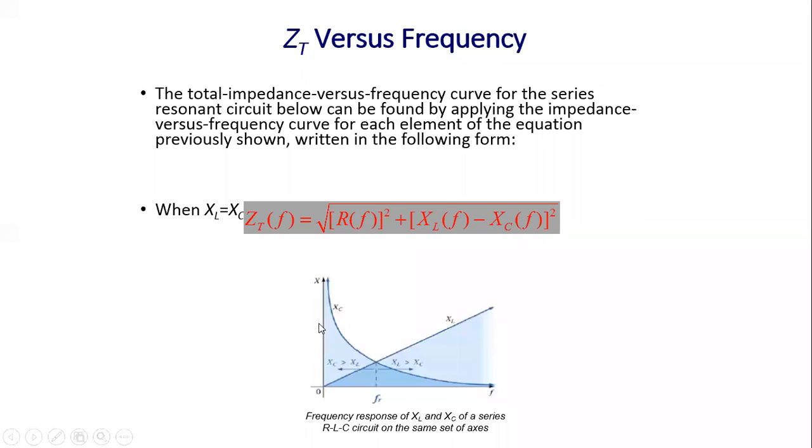So you see here, this curve is clearly showing the separation. This middle part is where the curve of XC and the linear curve of XL cut at a particular point, and at that point I am getting the resonant frequency, that is FR, or you can say FC. In this previous section you can assume my capacitor value is greater than the inductor value, whereas here the inductor value is greater than the capacitor value.